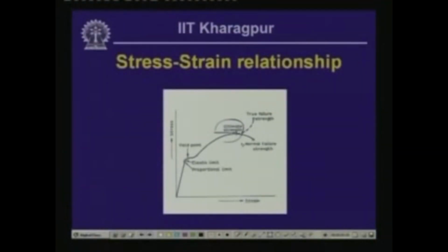Now, in this particular experiment which we have seen just now, we have not reduced the cross sectional area as such, we have applied a pull to the bar, but the whole bar was marked with segments of 40 millimeter. After the application of the tensile pull, the segmental lengths which were originally 40 millimeter were measured again, and in the segment in which the failure had occurred, we measured the extension, which we found to be around 14 millimeter. Now, this gives us a measure of how much elongation the member can undergo before it really fails.